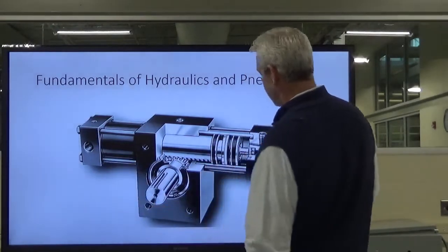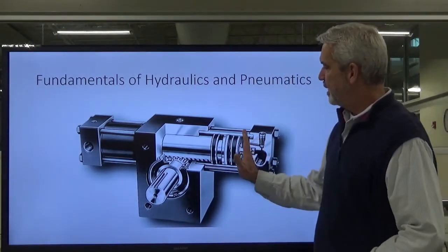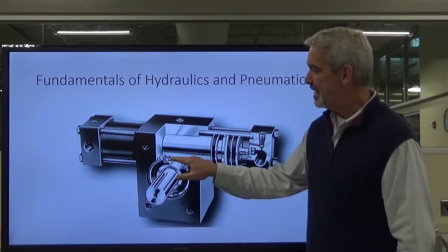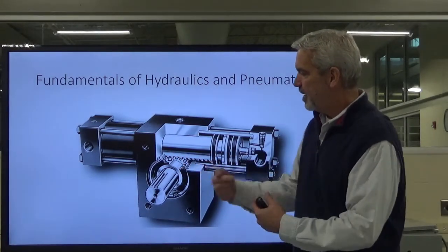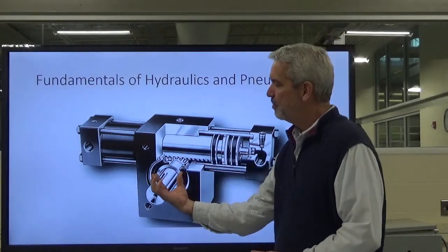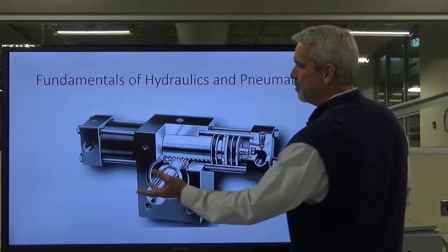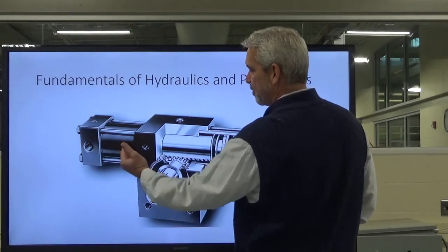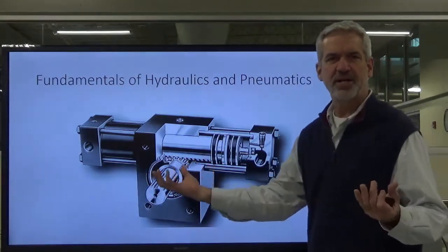You've got two cylinders on each side, and here's your piston right here. You pour oil to the back side, it pushes that cylinder, and I don't know if you can see very well, but this is kind of a rack and pinion. It's got teeth on the bottom side of this half of the shaft, and there's a 90-degree set of teeth running the other way. When we push the cylinder this way, it's going to rotate the actuator this way, and then once we've traveled as far as it will go, we can pour oil to this side, to this piston. It will then push oil this way. The actuator will then move back, so your actuator can move 45, 90 degrees, something like that.